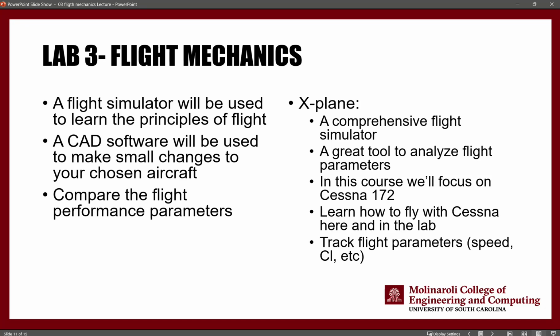And it also lets you record the flight performance data like lift, angle of attack, flight velocity, drag, and all of these other data. So the idea is you take this X-Plane, you learn how to fly with it, and we usually use Cessna 172 for this lab, but if you want to use a different aircraft from the library of X-Plane, you are welcome to use a different aircraft.